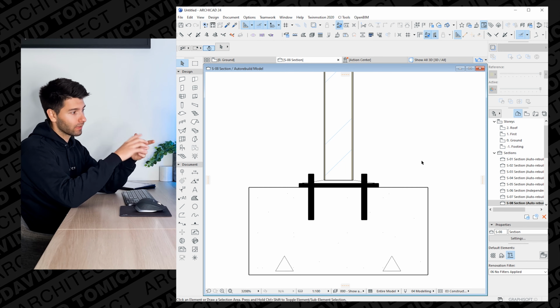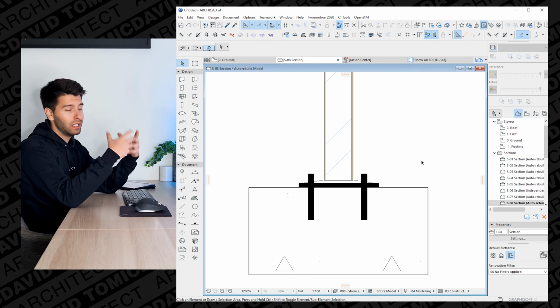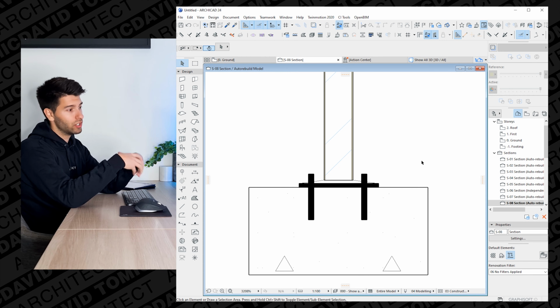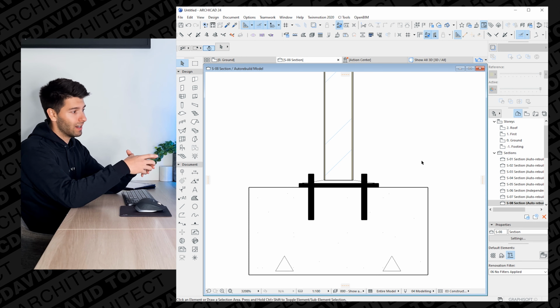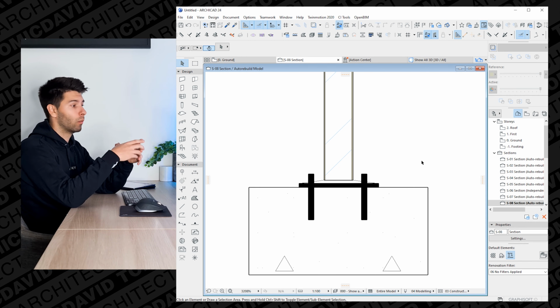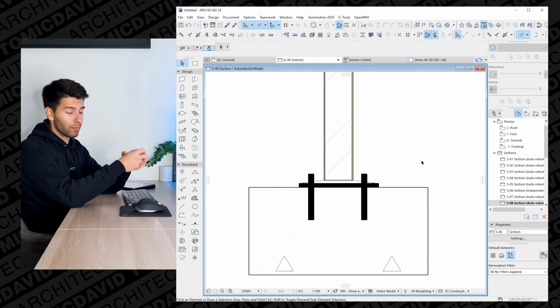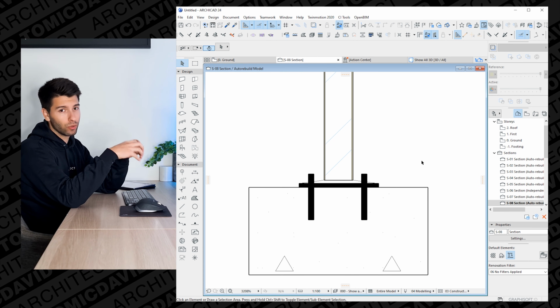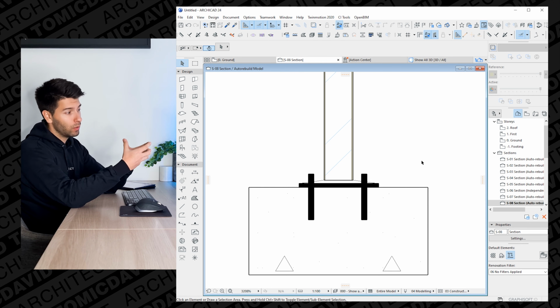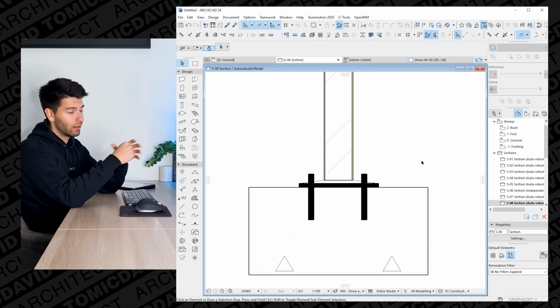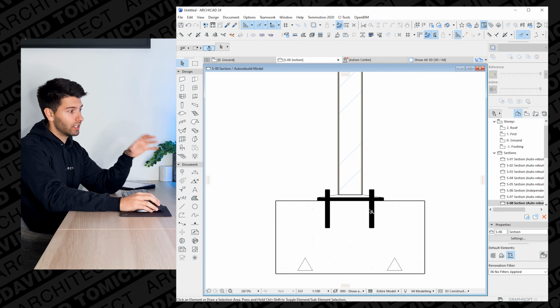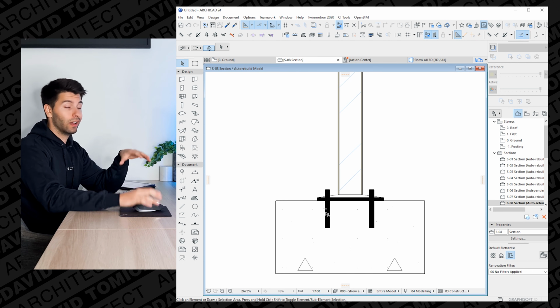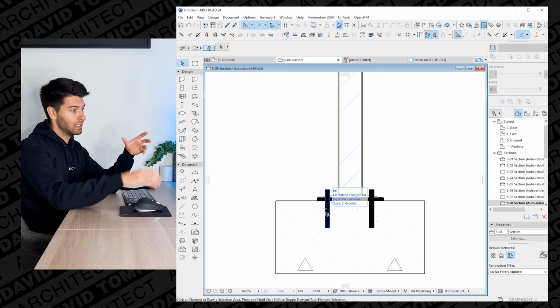that we're talking about. So the chemi-anchored bolt is something, again, depicted by the structural engineer, not necessarily defined by the architect, but it's something that we need to be aware of. It is basically a pre-drilled hole, a bolt goes into that hole, and then it is filled with some sort of chemical resin that expands, fills that hole up, and makes sure it is a very snug fit. From a sectional architectural point of view, this detail is horrendously ugly and industrial.